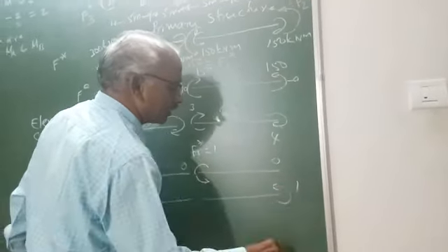This is equal to F2 star equal to unity. So when you apply F2 star equal to unity, this being a hinge, here it will be 0, here it will be 0, here also it will be 0. Therefore the second column will be in the same order 1, 2, 3 and 4: 0, 0, 0, minus 1. These are the system forces. So this matrix is called the B star matrix.